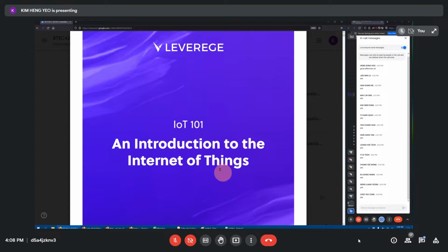In order for this communication to happen, you just need to add one more communication module to your microcontroller, and that is the Ethernet module. If your microcontroller doesn't have a built-in Ethernet peripheral, then you need an Ethernet module. But your LPC1768 has a built-in Ethernet peripheral. It already supports it, so you can directly connect the Ethernet cable to your microcontroller.